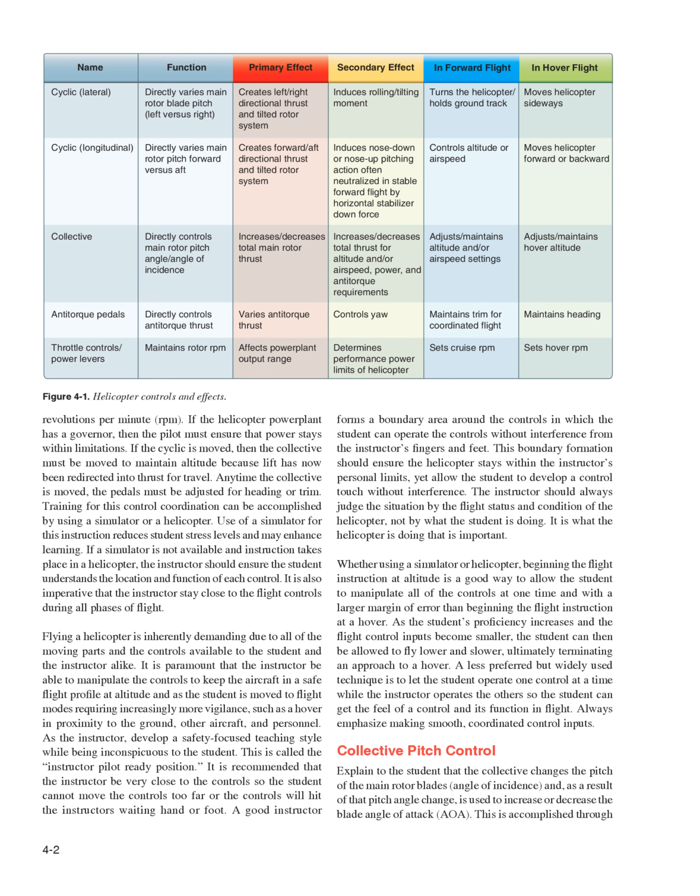A less preferred but widely used technique is to let the student operate one control at a time while the instructor operates the others so the student can get the feel of a control and its function in flight. Always emphasize making smooth, coordinated control inputs.